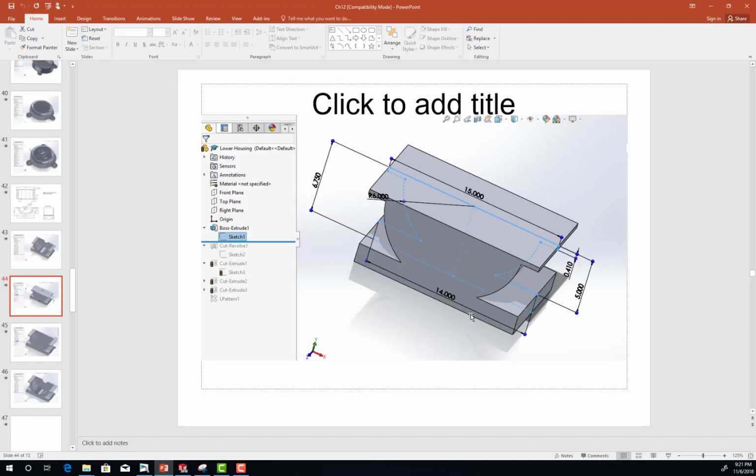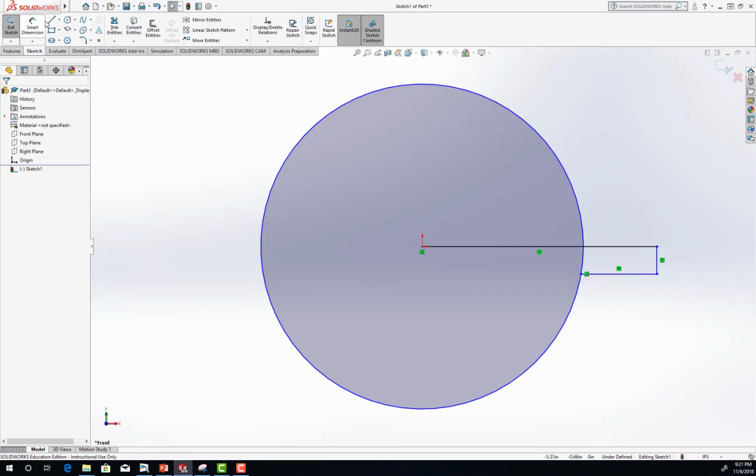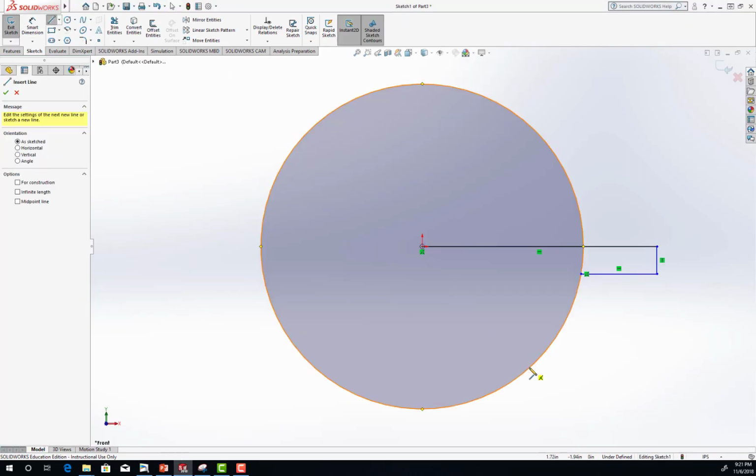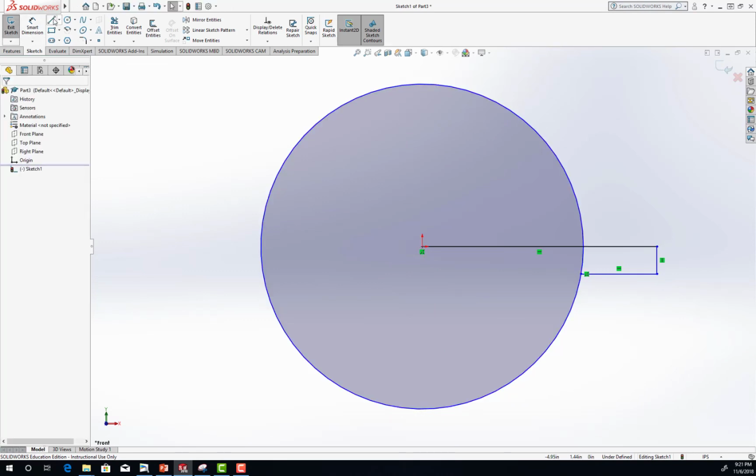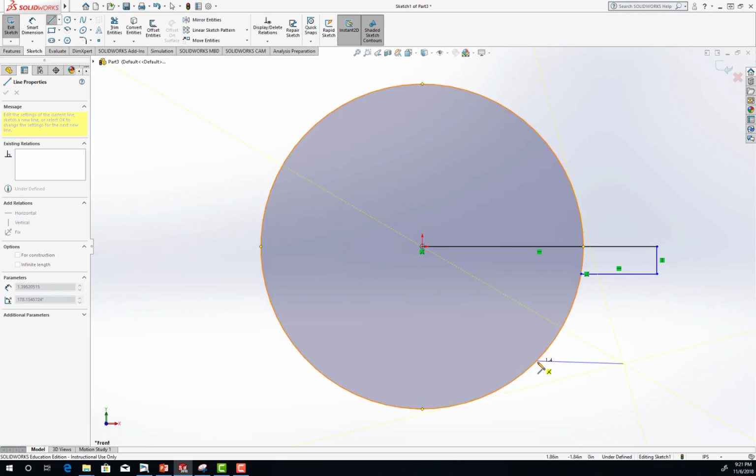Then let's go back, then go right, go down and close the shape. Then go to the dimension, so go here. Whoops, I recognize that's not what we want. So we're going to start from the other direction. So make it coincident with the circle. Make sure both coincident and horizontal relations are showing up.